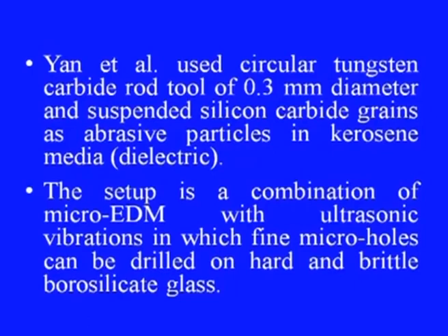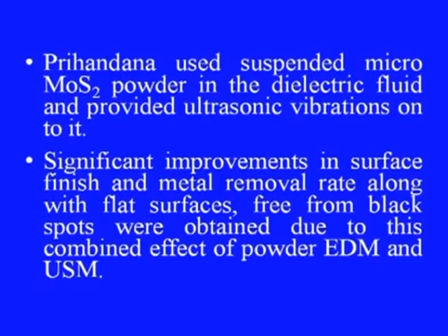Yan and his co-researchers used a circular tungsten carbide rod of 0.3 millimeter diameter and suspended silicon carbide grains as abrasive particles in kerosene media, which works as a dielectric, in another attempt at hybridization of this process. The setup is a combination of micro EDM with ultrasonic vibrations, in which fine micro holes could be drilled on hard and brittle borosilicate glass.